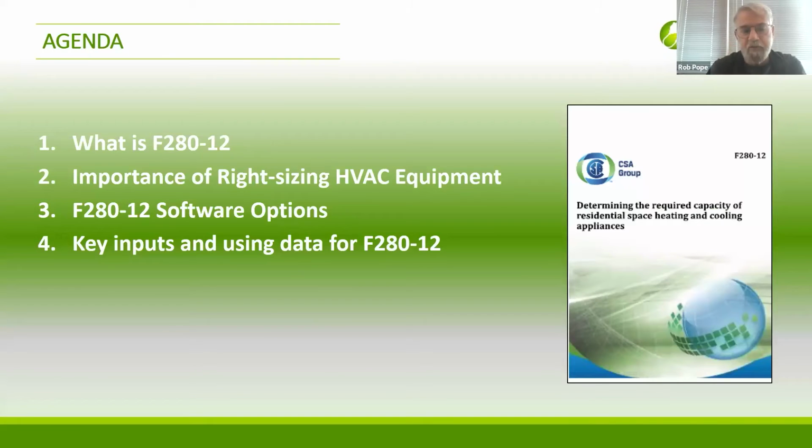Today, we're going to go through 4 major topics. First of all, introducing what F280-12 is, and following that, the importance of right sizing HVAC equipment, things that can go wrong. I'll give you some real life examples, and the options for F280 software, including verification and the key inputs using data for getting the right output for your load calculations.